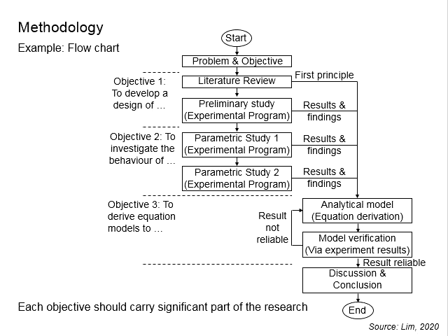You know that with the significant reduction in the number of specimens, there is a risk of a lower confidence level. If you have only 1 specimen for each parametric design, any errors, mistakes, or defects which happen during the production of your specimens may affect your data, and you might not be able to check the reliability of the results. These are all the things that you have to take into consideration while designing your parametric study. Now let us come back to this.